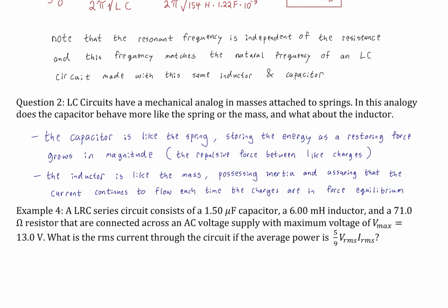Likewise here, there would be some distribution of charges throughout the entire LC circuit, where all the electrons are at basically their maximum distance apart. That would just be how the circuit would be at rest, but it doesn't get to that state because the inductor, due to the fact that it responds to changes in current due to Faraday's and Lenz's law, effectively acts like inertia and continues pushing the current right through the equilibrium point.